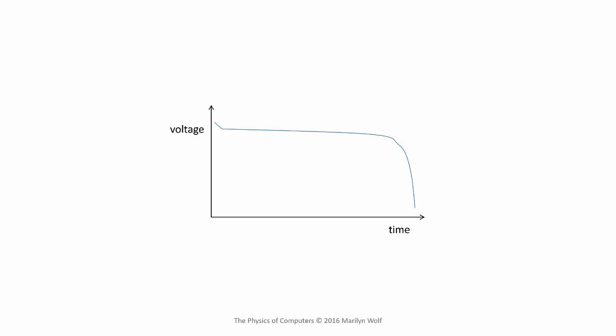The discharge rate of batteries helps us determine when the battery is about to run out of power. This is a typical voltage versus time curve for a battery we might find in a cell phone or a consumer electronics device. Earlier in the discharge cycle, the voltage is pretty flat. It may vary a small amount, drooping slightly, but it will be pretty consistent.